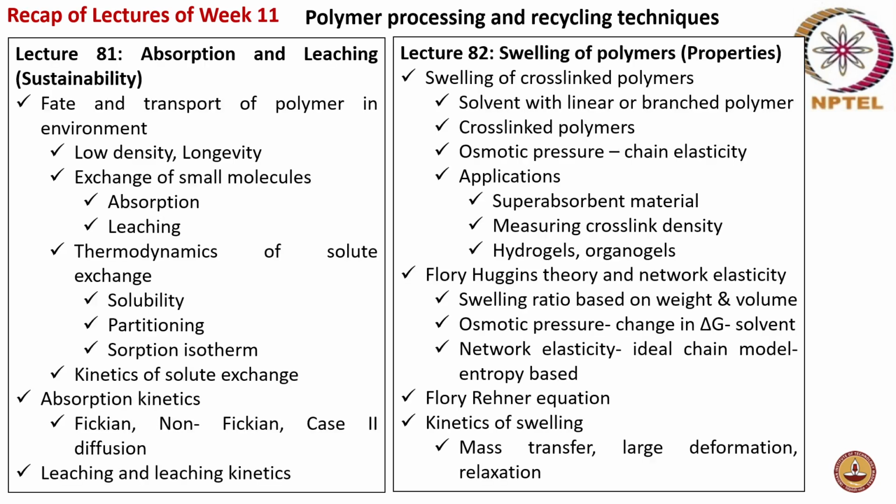Next, lecture 81 was on absorption and leaching. So this was a lecture on the sustainability aspect. What is the fate and transport of polymers in the environment? Because of their low density and longevity, and what is the exchange of small molecules? Small molecules taken up by the polymer is absorption, and coming out of the polymer to the external environment, whether it can be another polymer, or a liquid phase, or a gaseous phase like air, or a soil environment, that is leaching.